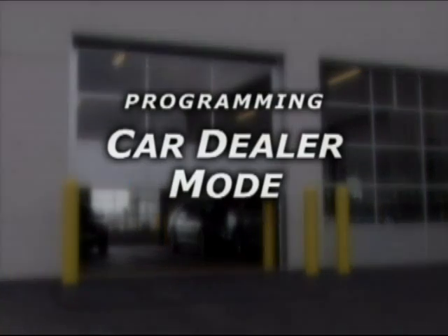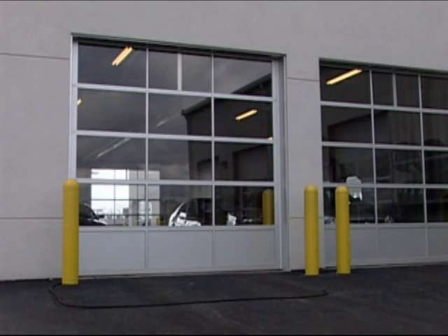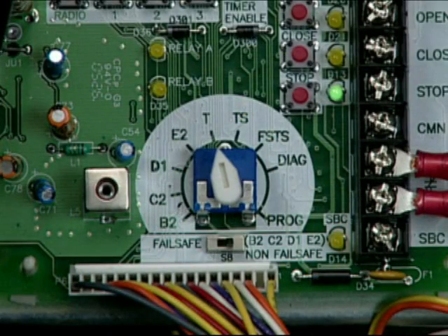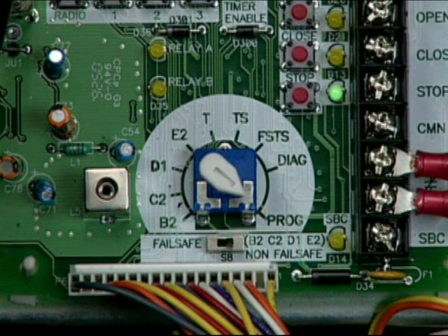Let us now review the programming steps in setting up the car dealer feature. Begin with the door in the fully closed position. Turn the selector dial on the logic board to Program. Press and release the timer button on the logic board. The timer enable LED will turn on. Press and release the MID button and the timer enable LED will blink rapidly 6 times. Press and release the timer button and the timer enable LED will turn off. To finish programming, turn the selector dial back to the desired T, TS, or FSTS wiring type.